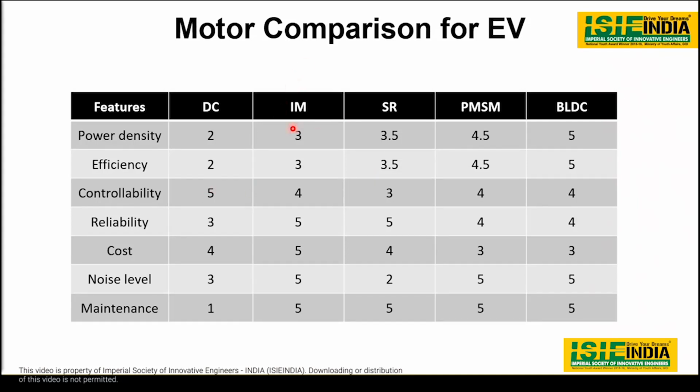You can use the variable frequency drive for the induction motor. You can use the variable frequency drive for the SRM, PMSM, and almost all BLDC is having that variable frequency drive inherently. That is different. That is why this is electronically commutated, right? This is also electronically commutated. This is not electronically commutated, PMSM, and this is not electronically commutated. These two are naturally commutated. That is the beauty of Nikola Tesla. Okay, right? But this DC motor is having the commutator.